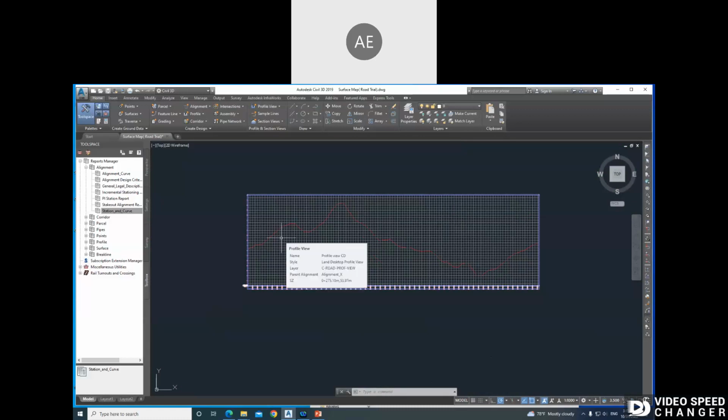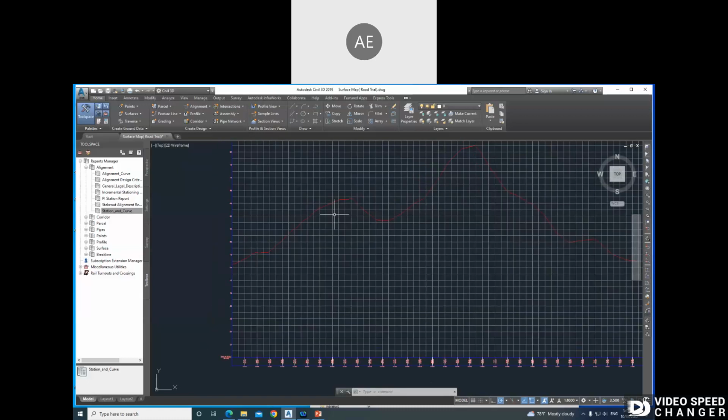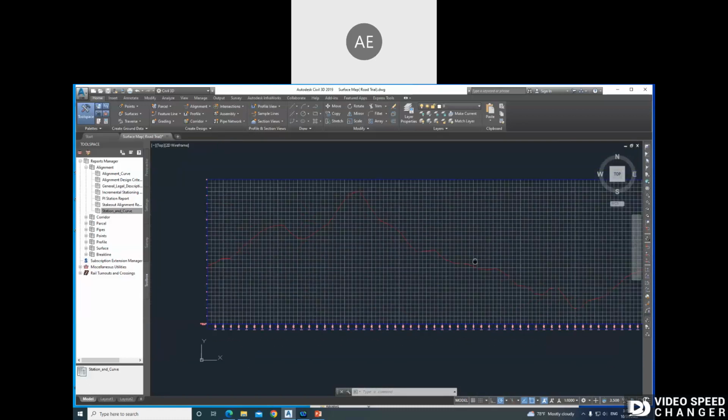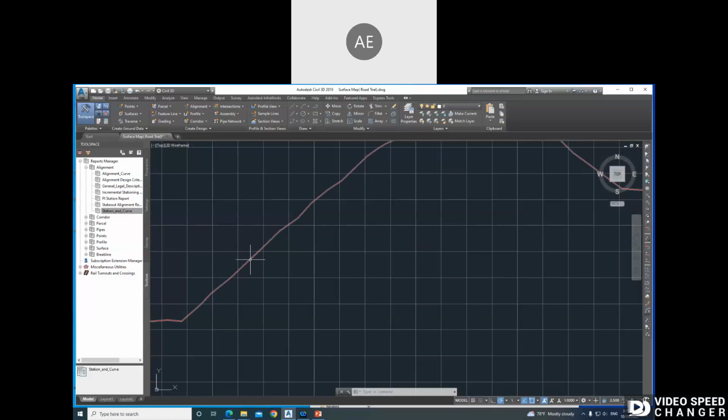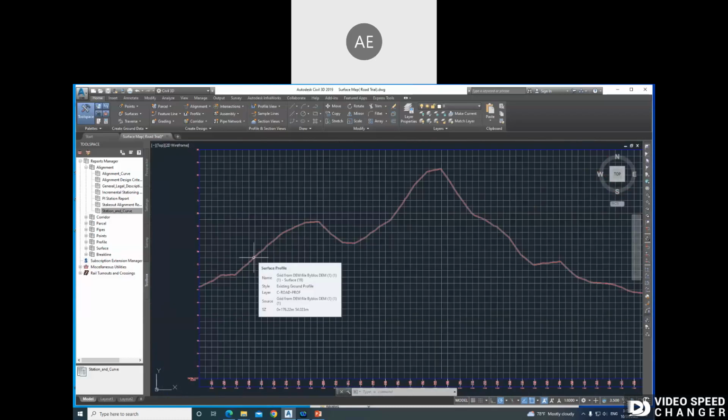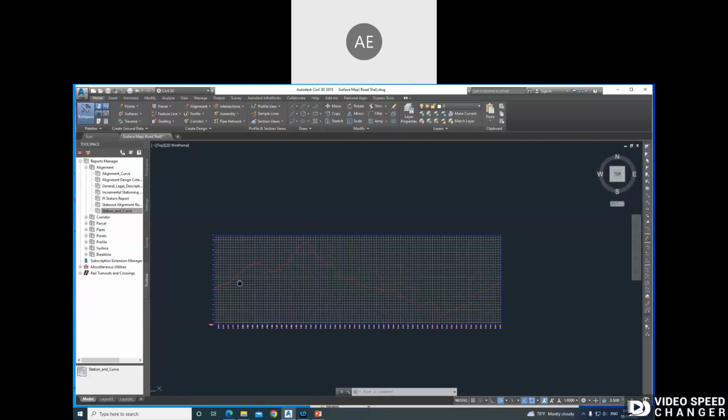And of course, if I check it, look how the elevation is changing. It's not consistent, so it is not adequate. It means we need to create a new vertical alignment. Why? Because at the end we have cars. It is not adequate for passengers. If they want to go from A to Z, they want to use cars. It's not adequate. To do that, we simply press on this one here.